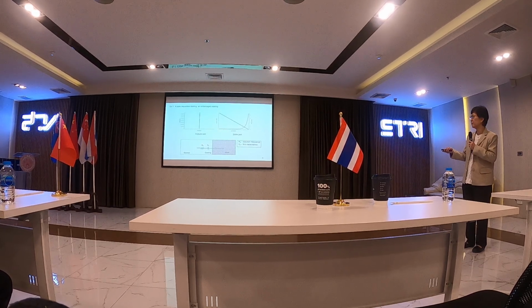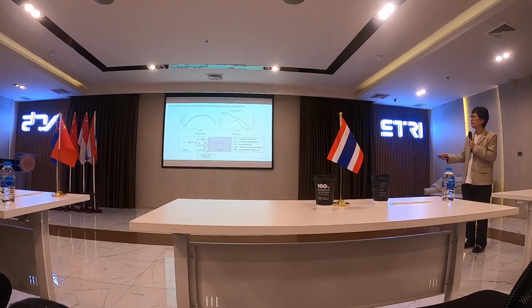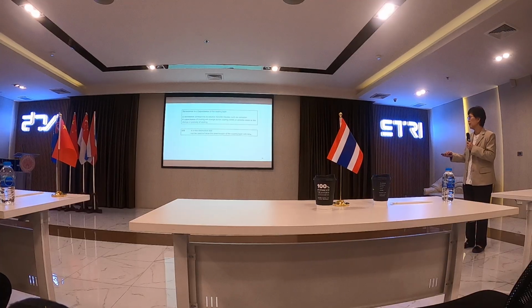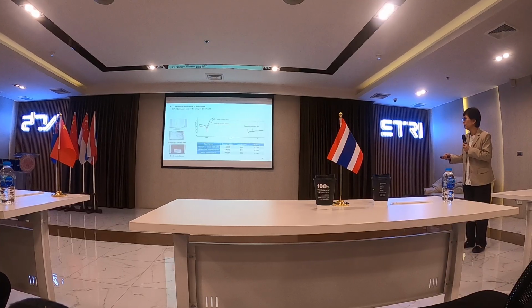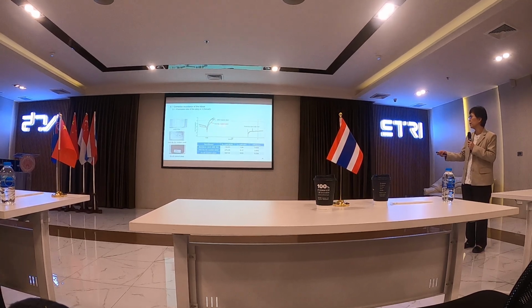For example, like this, we have a pure capacitive coating, then the solution can penetrate the coating, and then the solution can reach the metal substrate. This is the application that we use. This is for testing different types of coating and stainless steel.